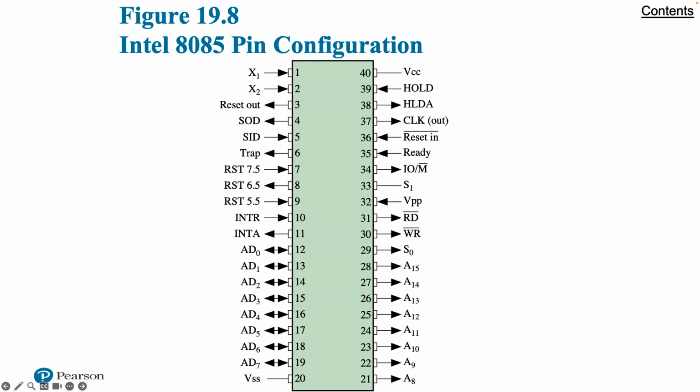The control unit is identified as having two components labeled: one, instruction decoder and machine cycle encoding, and two, timing and control. The discussion of the first component is deferred until the next section. The essence of the control unit is the timing and control module. The module includes a clock and accepts as inputs the current instruction and some external control signals.